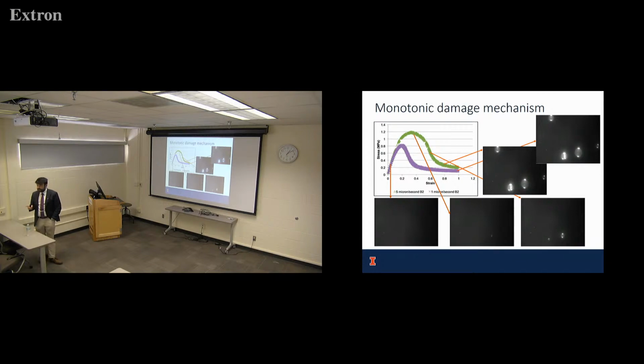Yeah, so this is a good question. So just first with regard to the first point, the triaxiality in our case, I think in your case it's an input, in our case it's the output. So we're actually trying to determine what is the triaxial state of stress. I think in your test you're trying to determine what is the material property based on a known triaxial state of stress.